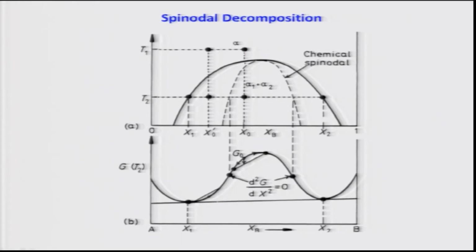because now you know what is quench. We have discussed a lot about quenching martensites in steels. So let us suppose I take this alloy and quench from T1 to T2. As you see, at T2, the alloy will have a free energy given by G0 here, because this is also the composition axis. So at x0, it will have a free energy of G0, and a dotted line can be drawn, and so on.